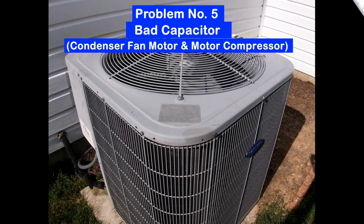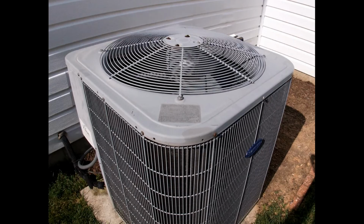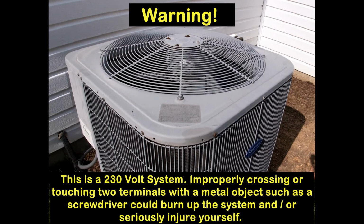If you can hear your air conditioning system come on and both the condenser fan motor and motor compressor try and fail to start with buzzing or humming sounds, you most likely have a bad capacitor. Most air conditioners use the same capacitor to start the fan motor and motor compressor, so if both fail to start, the problem is most likely the capacitor. It's critical that you're careful with this 230 volt system. If you improperly cross or touch two terminals with a metal object, such as your screwdriver, you could burn up the entire system or seriously injure yourself.